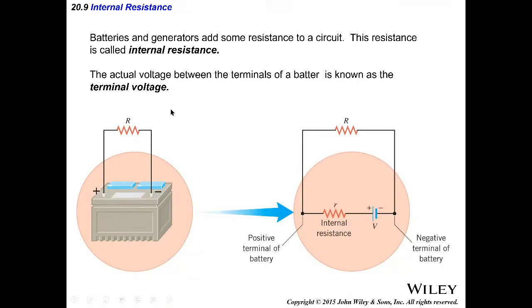And now we just want to continue on the issue of, if I have a battery, the battery actually has its own internal resistance. So even though I am connecting it to a battery that has a voltage of 6 volts, the internal resistance is a little r, and the outside is a lamp or whatever, the capital R. Then the actual current that flows is not V over R, it is V over capital R plus internal resistance.